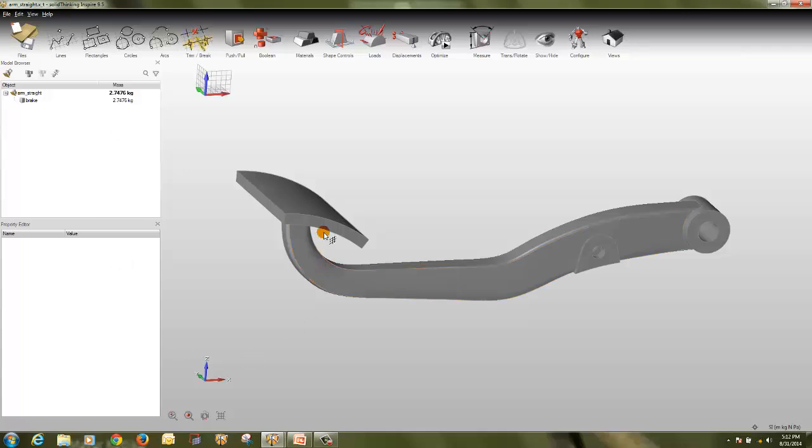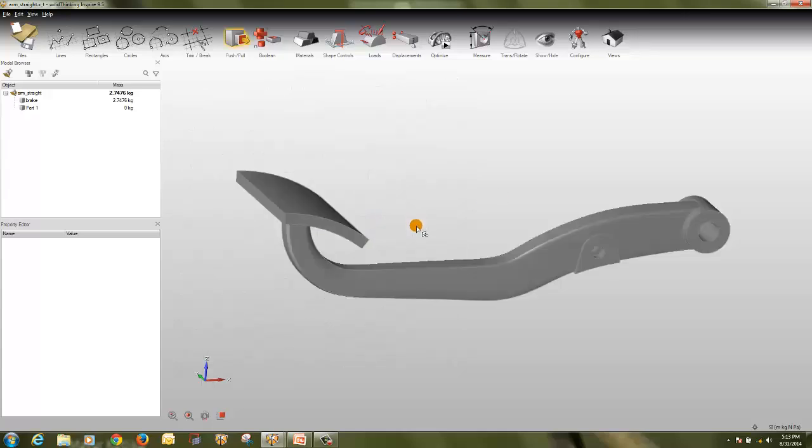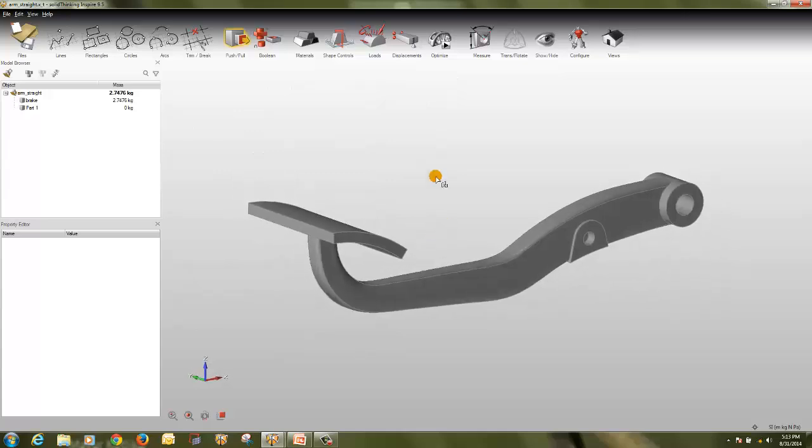We'll use the break, create new part, click on create new part, then click on this line and select create curves from all reference lines. It will create an entire curve here for the new part. Then right click to select this part, again right click to finalize it. So we have created a reference surface of this.